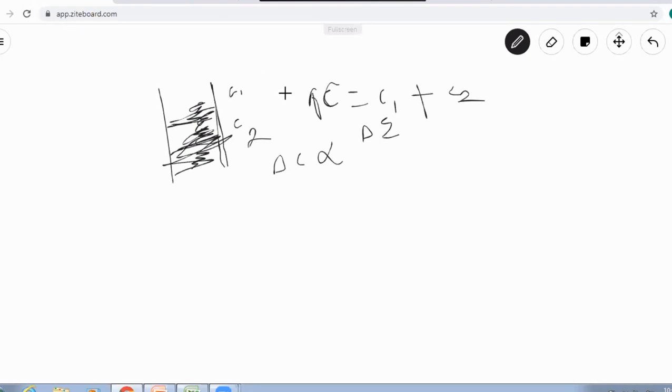Now this is the function, the change in capacitance. C equals epsilon A by D. So the change in capacitance del C is proportional to epsilon into A. The next thing is the distance. C equals epsilon A by D. Now if we vary the distance, meaning the distance between two plates, what is the input quantity? The change in input is the change in displacement, the distance.